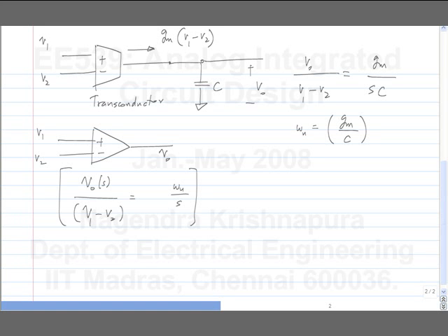So this is what we have so far. In terms of this, we know we want this from our basic analysis, and from our knowledge of circuits, we have this one. To get the integrator from the transconductor, we can simply load it with a capacitor. Of course, there are more and less complicated versions of the transconductor. We'll see why we need it afterwards. But this is one way of making an Opamp or an integrator that takes the difference between two inputs.